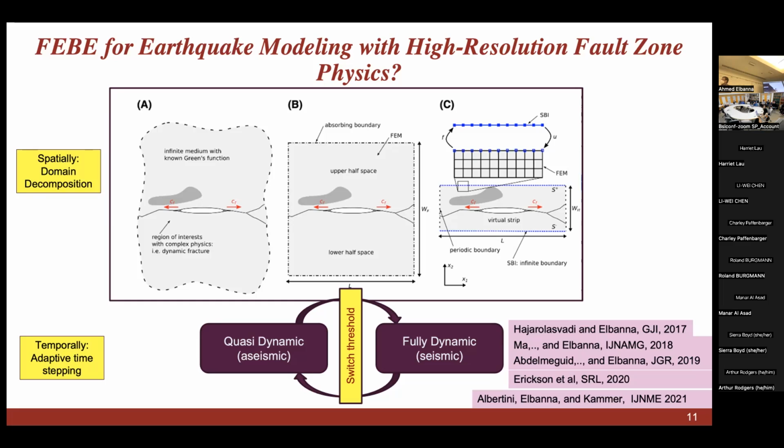For that purpose, we just need to augment the fault with a term called radiation damping, because if the motion accelerates towards seismic instability and we don't have this radiation damping initially, the problem can diverge. So this radiation damping just provides some kind of stabilization for the problem until we switch to a fully inertial formulation.